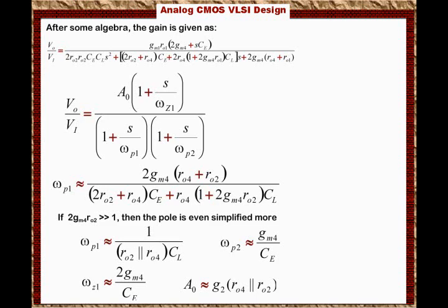So far we have described the frequency response of different topologies and different amplifiers. We used the Miller theorem approximation, and sometimes we derived the transfer function from scratch by drawing the small signal model, and sometimes by finding the equivalent resistance across each capacitor in the circuit we were able to obtain the location of the poles and the zeros, and approximate the transfer function.